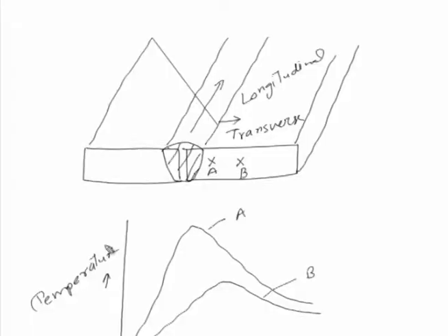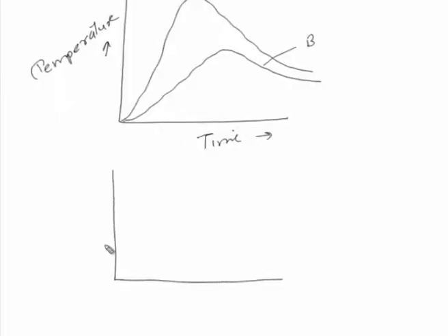So, the weld joint must be designed in such a way that the weld can be made using the least amount of weld metal and with the minimum heat input to the plates being welded. If we try to see the relationship between the residual stresses that develop and the weld metal being deposited, the amount of weld metal deposited and the residual stresses are very directly related, and we can see that the stress increases with the increase of the weld metal.